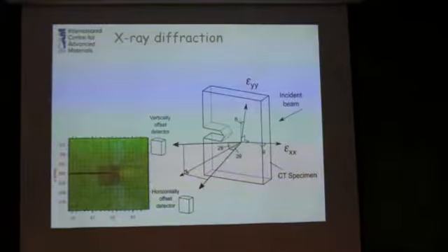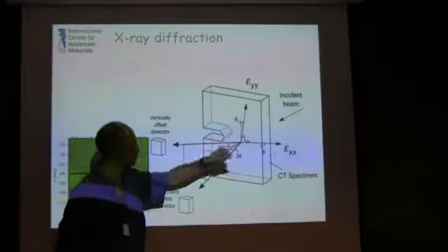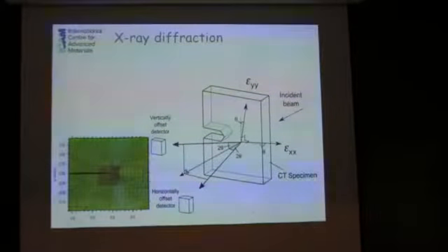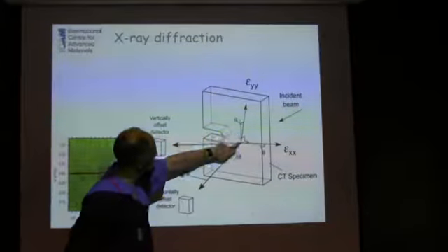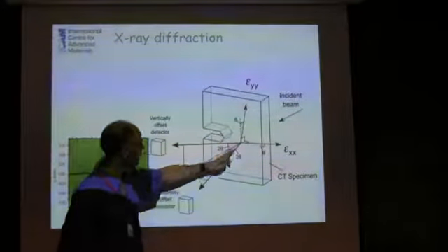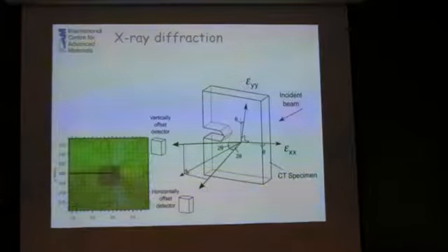And we do that using a white beam so that we can actually measure the whole diffraction peak at those angles. And because this is just 5 degrees, the diffracting angle is about 2.5 degrees. And so we're 2.5 degrees off in terms of the strain vector, but we're measuring a strain which is almost in the vertical direction, and we're measuring a strain that is almost in the horizontal direction. We're 2.5 degrees out, and I think that's fine.